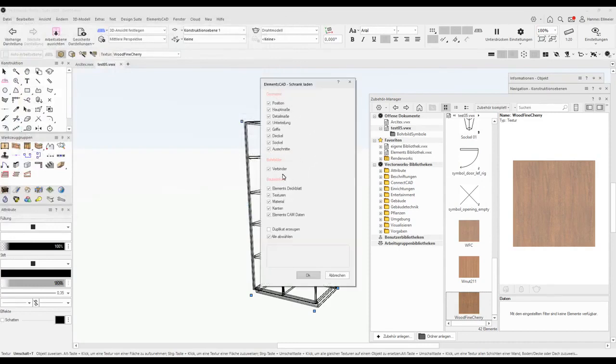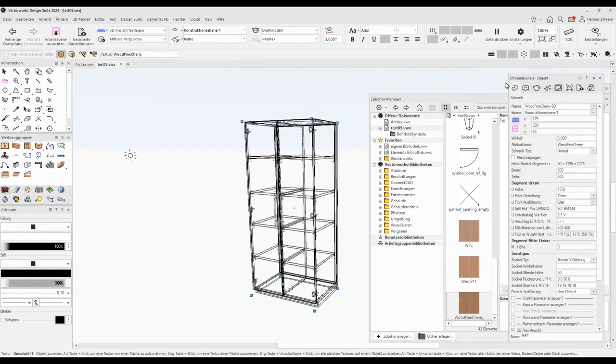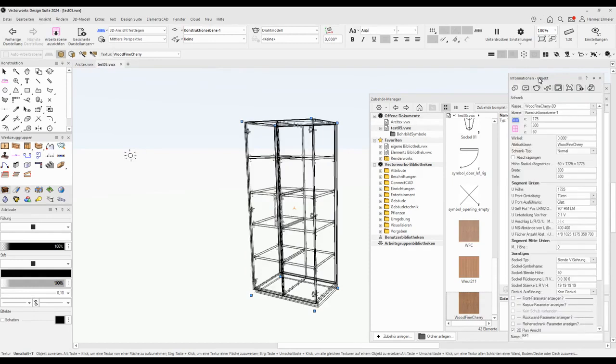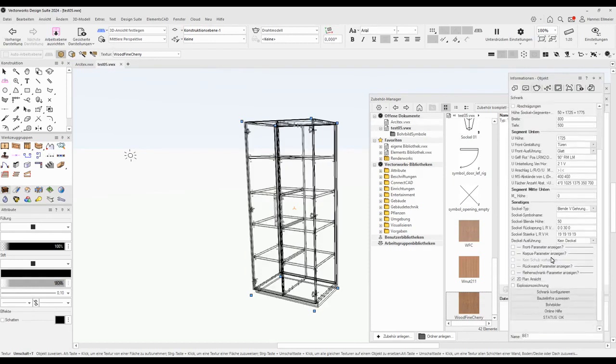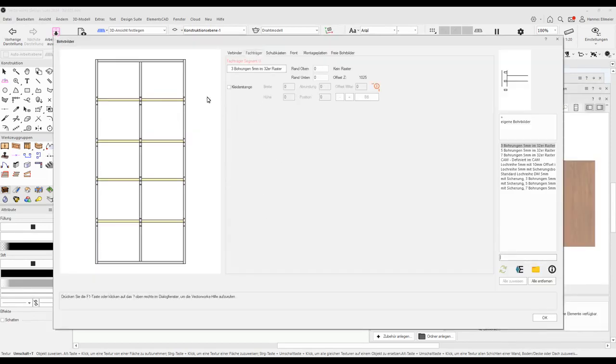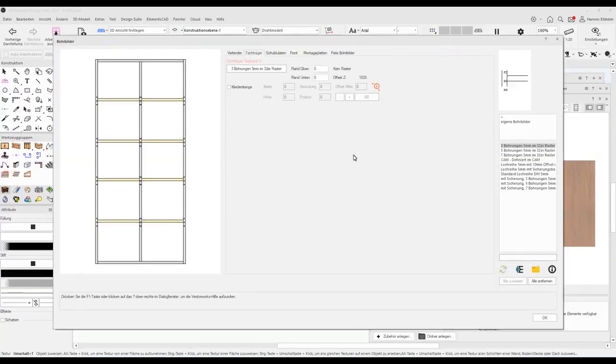As we can see here, the cabinet now has all the drilling patterns, but also other details like, for example, material or panel properties. We can go into the drilling patterns section here and see the assignment of drilling patterns. These drilling patterns, in turn, are provided by ElementsCAD. Here we could make changes to the drilling pattern, save it, and within Vectorworks, update it. We see the same for connectors, fronts, mounting plates, and the like.